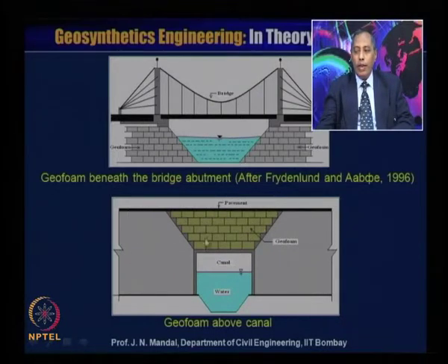So you can introduce this geofoam material, because if this is the concrete canal and water is passing through that, and you want to construct this road or embankment here, you can simply fill up this gap and construct this embankment.